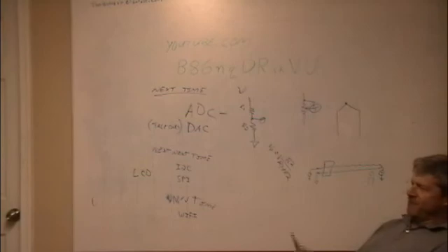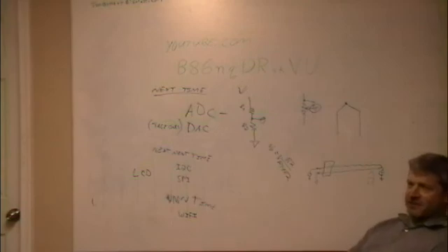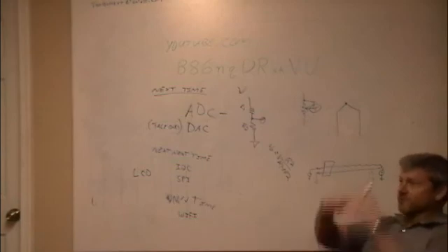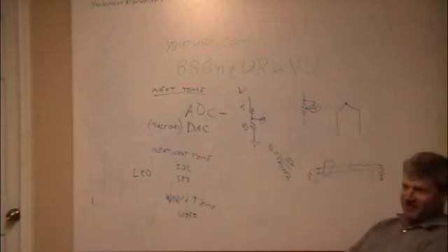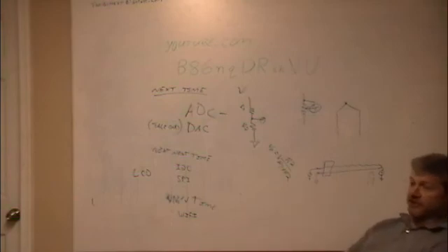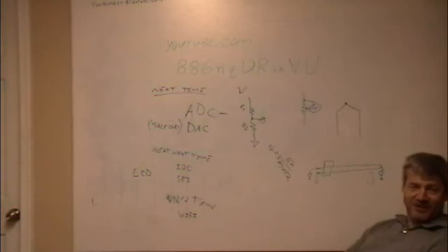And if you just hook it up directly without an ice reference, your process control feedback, the temperature you read, will drift with the temperature in the room that you're in. And what the ice reference does is they're figuring that if you're going through all the trouble to put a thermocouple on here, you actually want to know what the temperature really is. Not just that it changed.